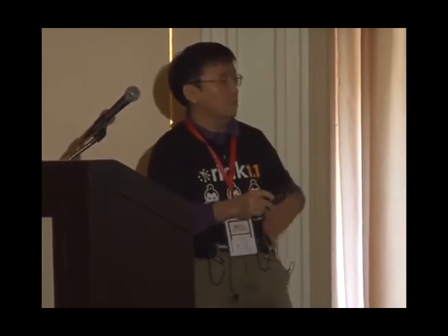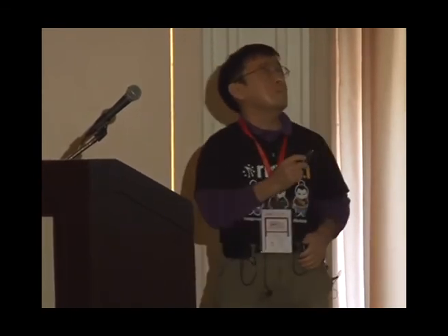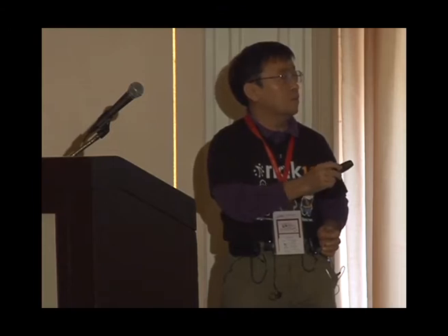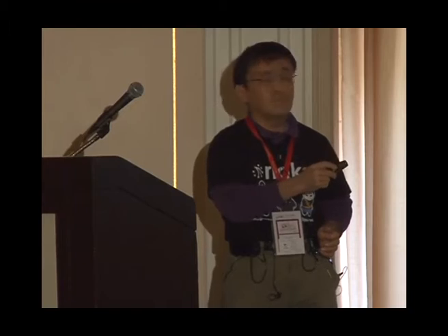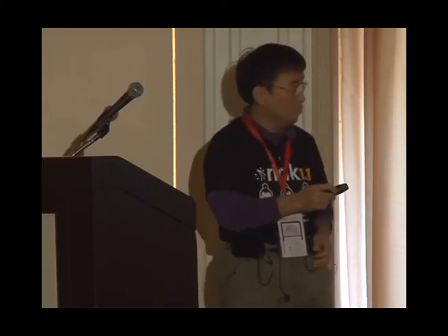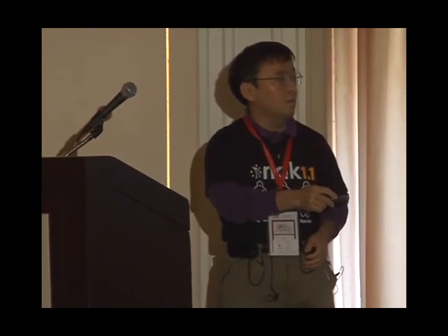So let me tell you about some tools of amateur radio, how to get digital data from amateur radio traffic. This is software called CW Skimmer. CW stands for Morse code. And this software skims the sound from the sound input, and it decodes the continuous stream of dits and dahs into the actual call signs, using Bayesian statistical analysis. And sometimes in a very crowded band, there will be 100 or 200 or many, many stations within a narrow bandwidth of 10 or 20 kilohertz.